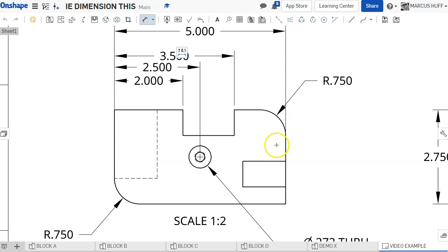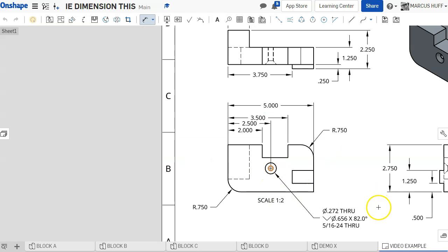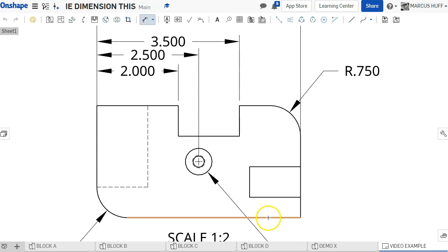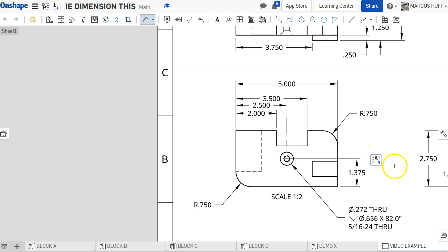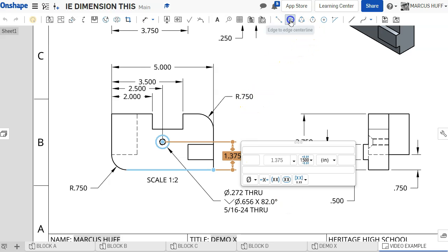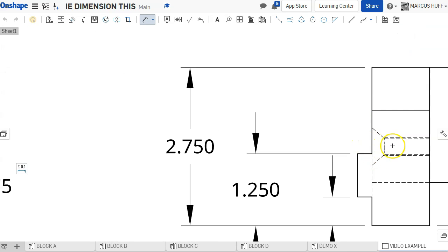And the other thing we need to position this is from this bottom edge to here. We can't show it on this side because it doesn't have a center line, or it can't dimension to a hidden line, so we're going to dimension this here. So we're going to go from the bottom to the center point, and it didn't catch right. So I'm going to try that again. We're going to dimension from here to that center point and pull to the right, center this value, zoom out, and now we know where to position that hole. And again, we're referencing from this bottom edge for everything related to height. One other line I want to add, we need to do a 2-point center line, so we're going to grab, never mind, I'm not going to worry with that. It's all not a problem.